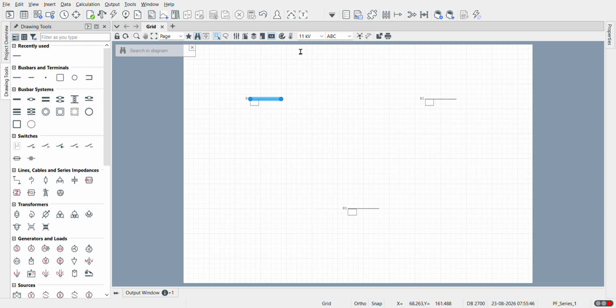Once we key in all the other parameters, we'll come back depending upon the bus system. For a basic system it is 1 for all the buses, but in some cases they will specify the bus voltage, and in that case we can change the target voltage as I showed you.